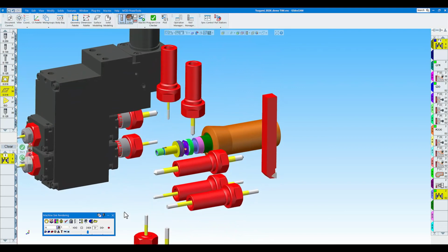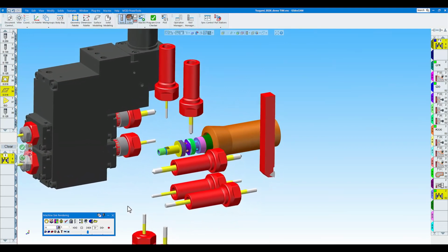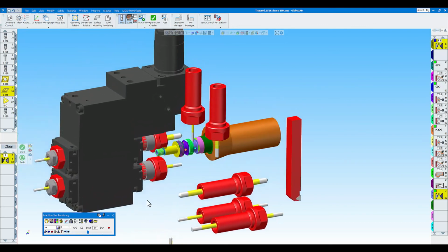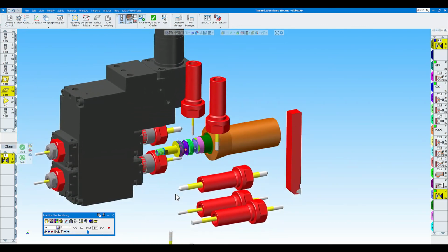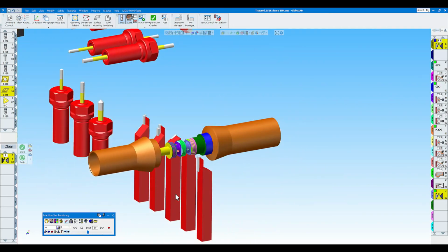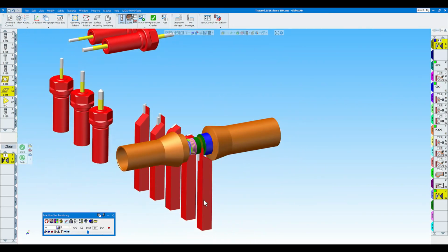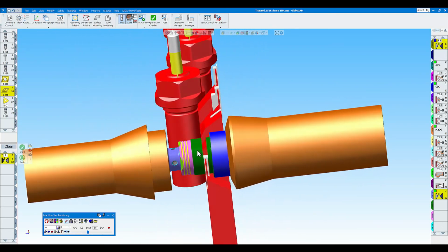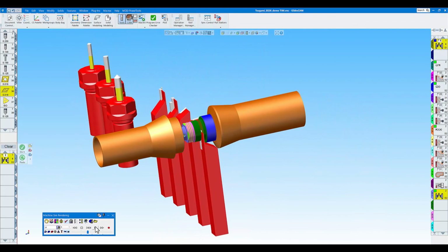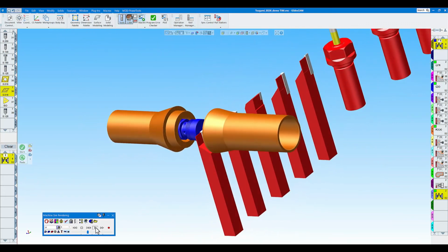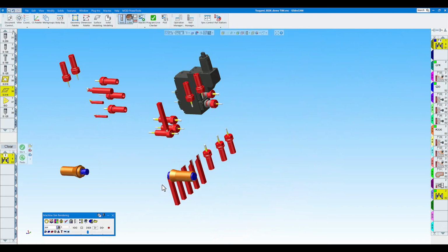The back part now we need to finish that by drilling and spot drilling and cutting the 45 degrees, finishing, and then of course the last grooves there. Sub spindle comes over, and as you can see we're in the midst of parting off. Click play, and it's in the sub spindle there, and back home on there.